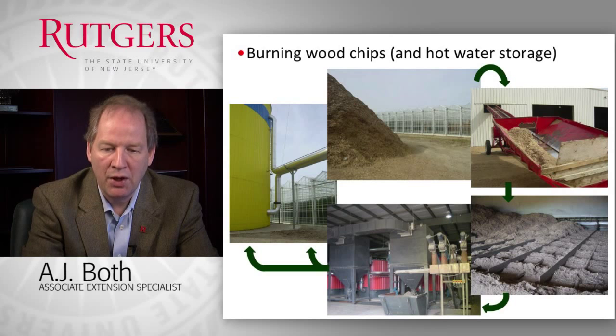We do that by running the heating system at its maximum efficiency as much of the time as possible, and then when we have excess energy that we produce with the heating system, we store it in the insulated water tank for later use. So by incorporating this storage mechanism with this biomass heating system, we increase the overall efficiency of our heating system.